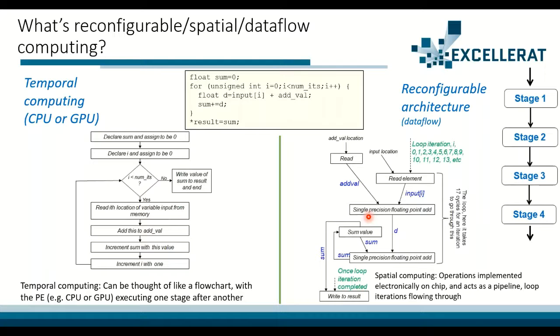And what we do is we shovel data in. So we shovel the first element in, which then comes into here, and as it's processing this, this is then working on the next element. And then this first element goes down here, the second element down to here, and then the next element here. And as I say, like a pipeline, once this is fully filled, then the idea is every clock cycle, we're producing a result. Because we have this massive amount of concurrency with our program, as I say, laid out on the chip and all the different parts running concurrently. Well, that's the idea at least.